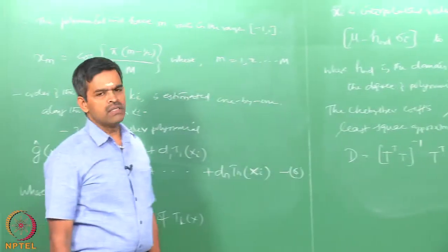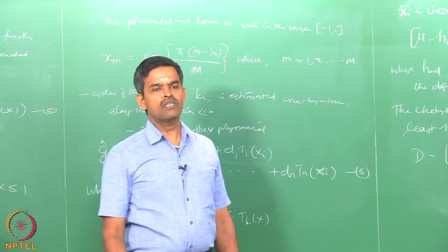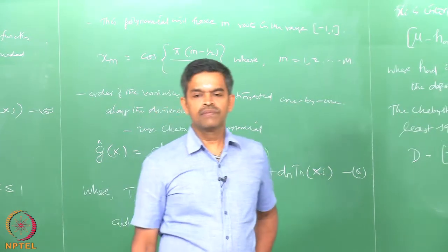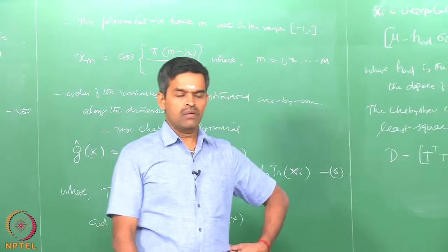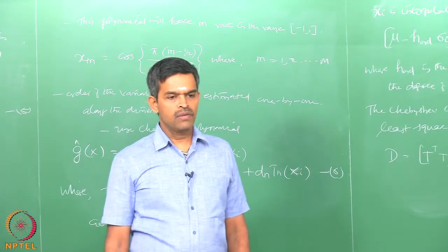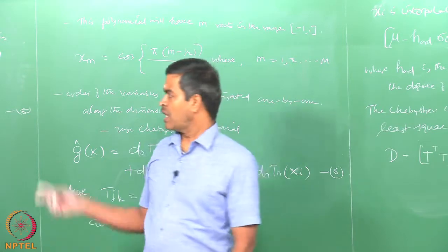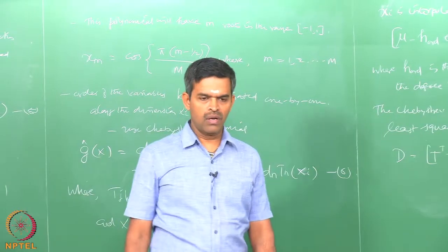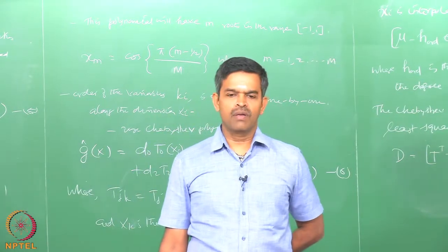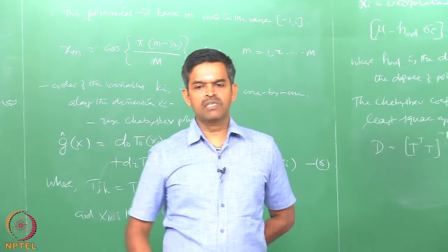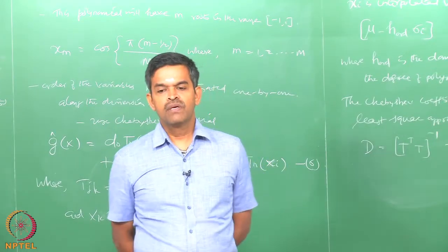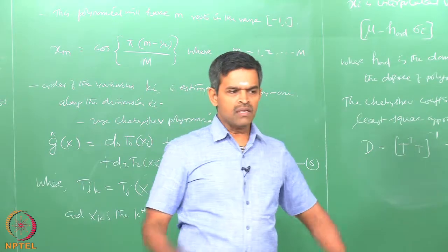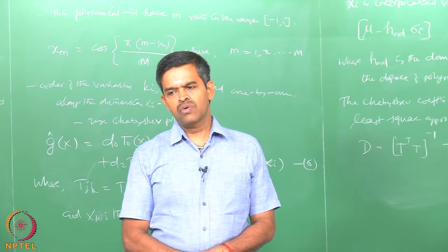Okay. Having understood different methods of linear first order, second order for normal, non-normal variate, using simulation methods, using higher order response methods, using Chebyshev polynomial where we are assuming or predicting the order of the polynomial which is going to represent the limit state function or the performance function, based on which failure probability can be obtained, one can now apply these algorithms very clearly to the system reliability.